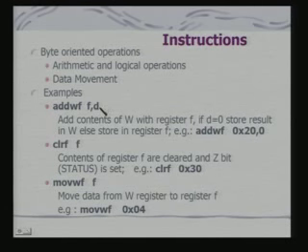In fact, D is indicating your destination bit, which we had discussed in the instruction format. So, actually when you will be using this, you will be writing it in this form. This actually represents a memory location in the bank, and this memory is part of the PIC chip itself. It is in the register bank. That location you are specifying, and then you are telling this is 0. That means the result will be stored in W itself. So, you add the content of this location with the content of the working register W and store the result back in W.